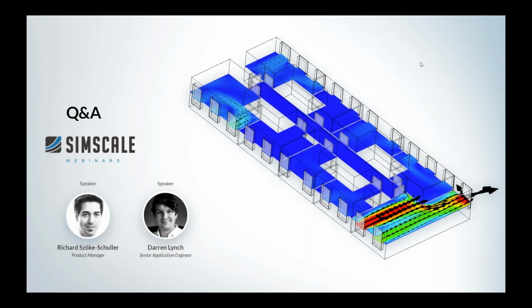The velocity in the kitchen is so much higher than the other rooms. Are the doors of the other rooms closed? I think that's quite an important question. So a fundamental understanding of this project, yes, the wind going straight through the kitchen is unrestricted, completely unrestricted. The flow that would be going through one room into the corridor and out the other side is restricted by the doors. The doors are modelled as closed with a very small leakage applied to it. So that's why we're not getting the vast through flows that we would expect if the doors were open.